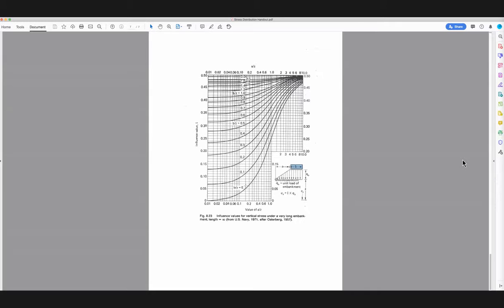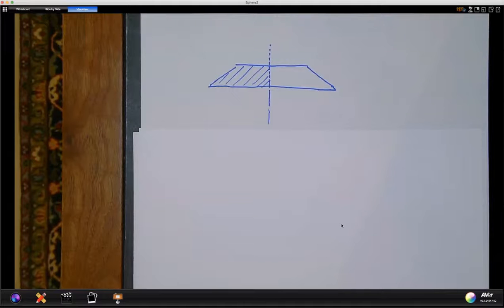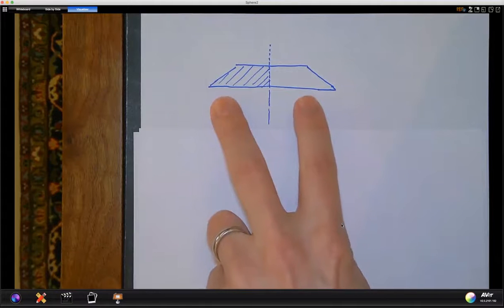That would put us on the high curves here, up in this region, the high B's, and it would put us on the high A's over here. So our influence factor in this chart is the y-axis, and we end up with an influence factor for that, what is shown in the graphic here, 0.5. And that's the rationale on this being appropriate, that you can simply multiply by 2.